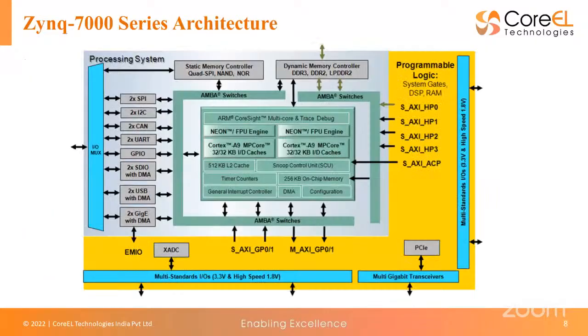So when we talk about the 7 series architecture, specifically the Zynq architecture, which is the SoC, system on chip, we have a multi-core processor available on the chip, along with the programmable logic, with a tight integration between these two using something called the AXI protocol. Using this, we are able to achieve the dynamic performance that an FPGA can offer.